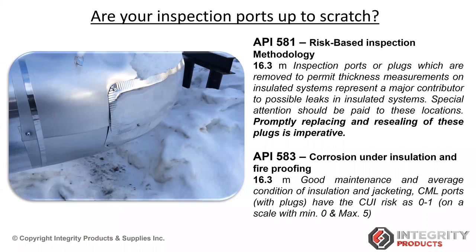Absolutely. That's why API 581 emphasizes that the inspection port system, although it's good for data acquisition, needs to have its plugs promptly replaced and resealed. Normally, as Karl, you mentioned, they can reseal with silicone, but silicone is not a long-term solution. Degradation can happen easily over time. Yes, the silicone is definitely going to be one of those maintenance items that needs to be re-siliconed every 1 or 2 years. And you'd have to ask yourself, is the inspector going to re-silicone when he does the test? So it's critical that those items are done.